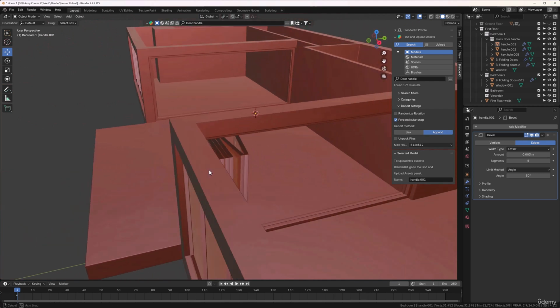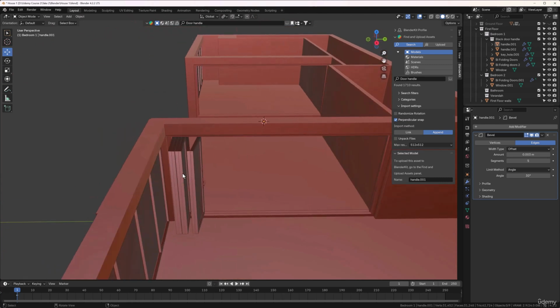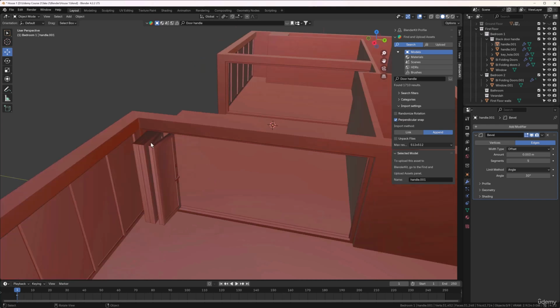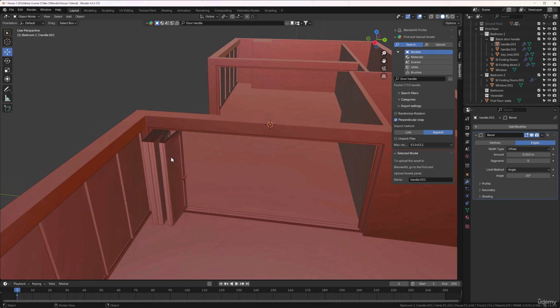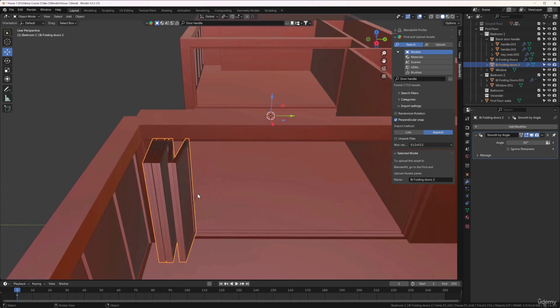And there's a very good reason for doing that, because when you use Alt D instead of Shift D, the 2 components share the same information. So when I apply textures to these doors, the same textures will be applied to these doors. So it's going to save us a lot of time in applying glass textures and wood textures to these doors, because it'll automatically do it on the opposite one as well. And also, it will also help reduce the file size too, keeping our file size as small as possible. So that said, let's grab these doors and the handles.